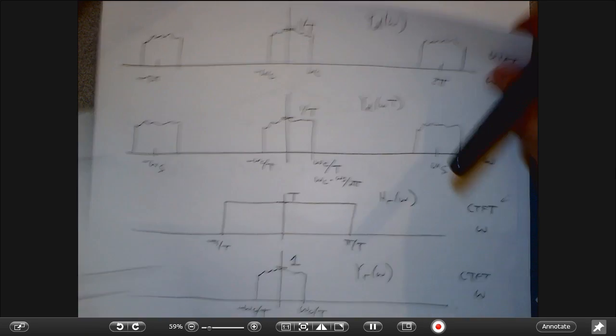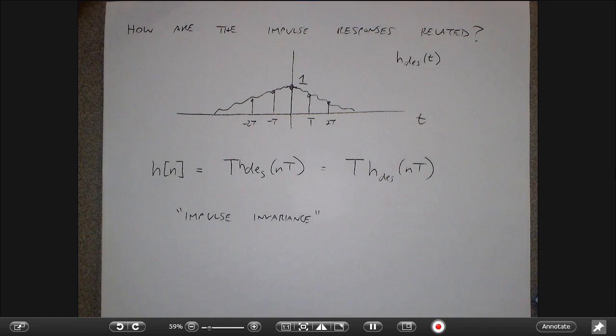And that results in this scaling of the effective frequency response of the filter. So you might look for questions on the next exam along the lines of: I want to design a filter that in the continuous time domain has a cutoff of 10,000 hertz. I sample that signal at 40,000 hertz. What should the cutoff in the digital domain be? Pi over what? That kind of thing is just a question of understanding how to convert back and forth between cutoffs, sampling rates, 2 pi's and omega s's.